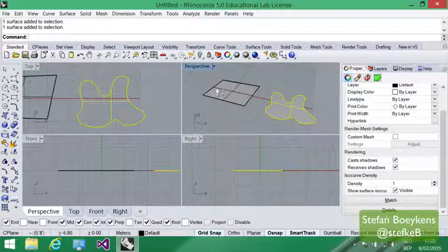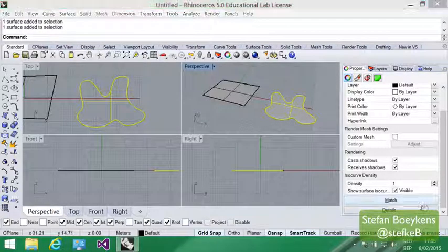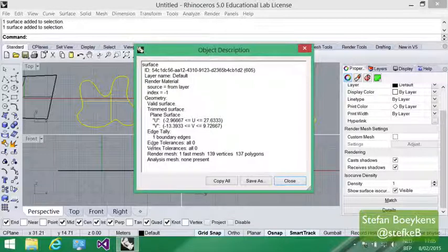Inside this surface, we can define subcurves, and we can trim the surface using the curve, which means that only the part inside or outside of the curve is retained. And in this case, this closed curve has been filled in with a surface that is actually a bit bigger, but is trimmed, and that's why we see here in the properties that we talk about a trimmed surface.